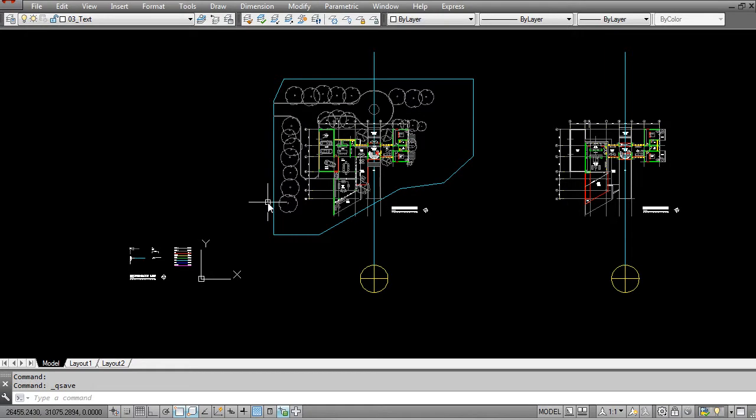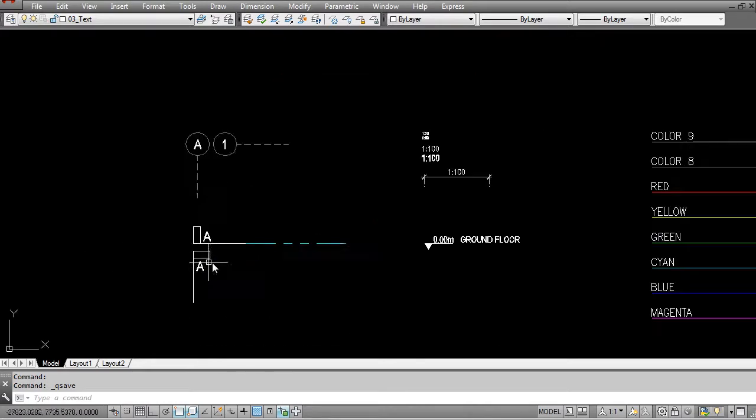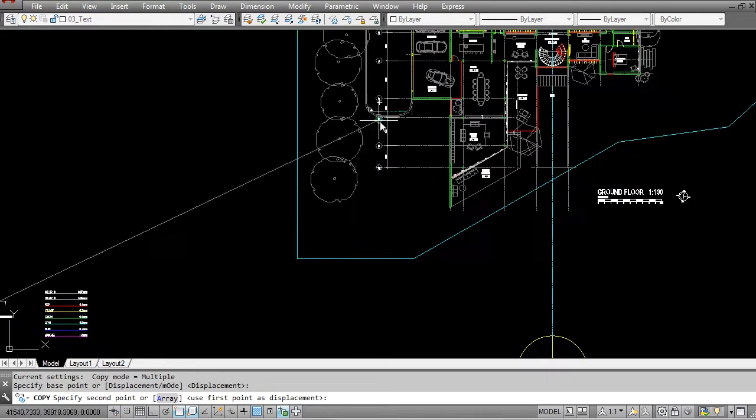For the case in our course, we're going to just do one of them and we're going to do one section. And we're going to have a look at how both of those have a very similar workflow, and we just basically carry on doing that same principle to all the different sides and all the other sections that you need to make for your particular project. So for these section lines, what we can do is copy the predetermined section that is here in our template. So I'm going to just select this one that is on the right hand side,